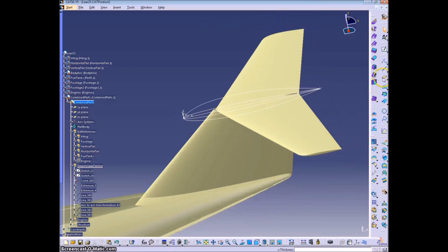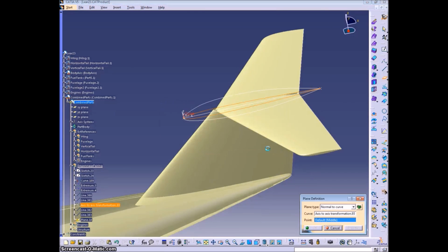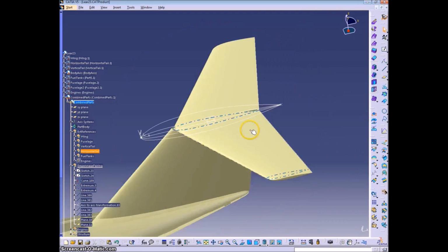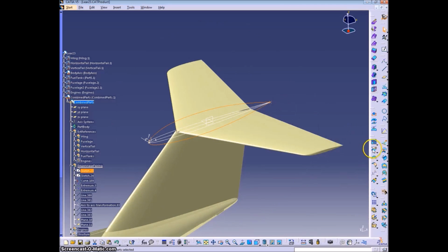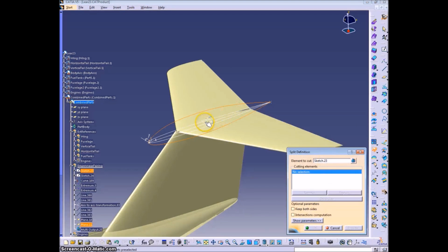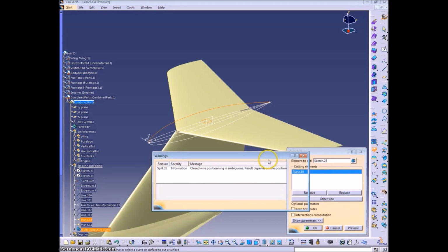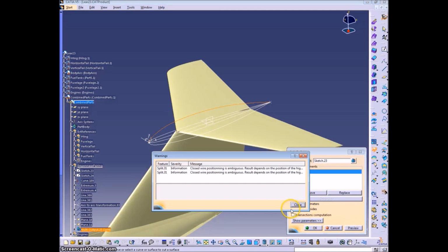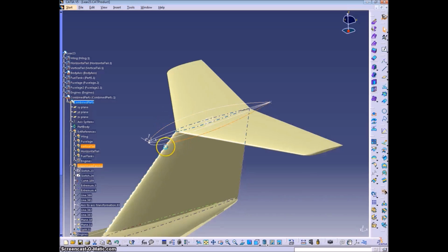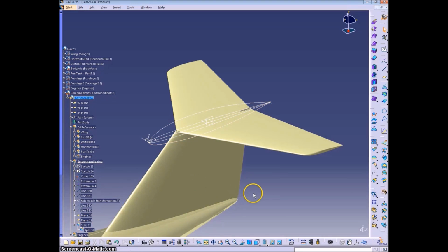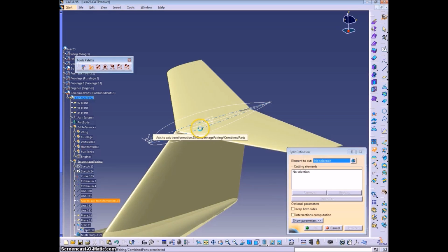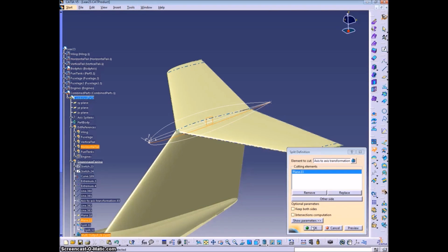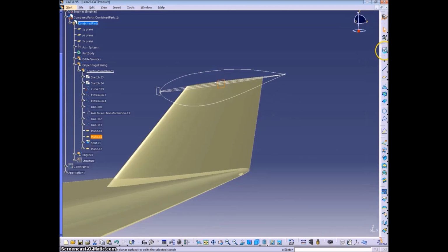And did an axis to axis transfer there, which got cut out of the video, pardon me, but if you go to the split command and go down 1, 2, 3, you can see the little two axes there. Click on that, and then you click on the profile you want, and then the original axes, and then the new axes, which would be the axes back here. And that'll transfer it. You can see more of that in detail in the structure section, if you can't figure it out from my description there. In the Laundron videos, there'll be lots of those. So here I'm just splitting all the guide curves.